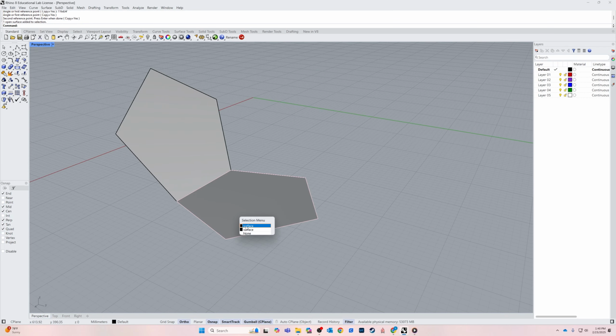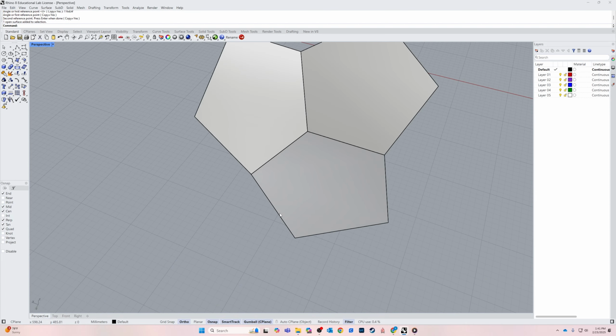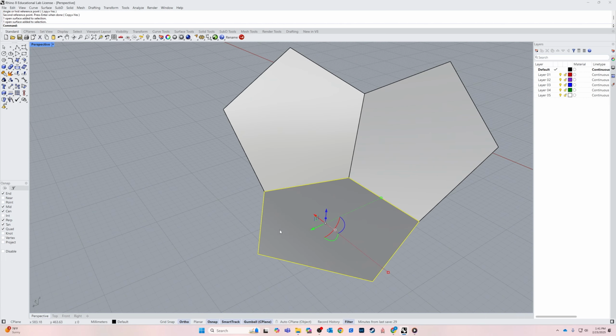And then we just do it again. Well, I accidentally copied 2 of them, so there's 2 there. So we go rotate 3D, specify my axis to there, drag out a little bit. So we got the little circle doohickey, and click. Oops, sorry. Do it again. Rotate 3D, axis, draft angle, 116D 34 apostrophe. Enter. Click. Escape. All right, I got 2 of them. And we're always checking to make sure everything is perfectly aligned, which so far looks like it is. Keep on going.